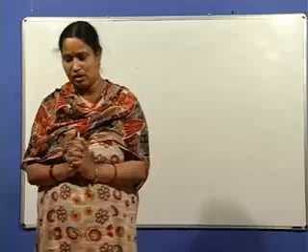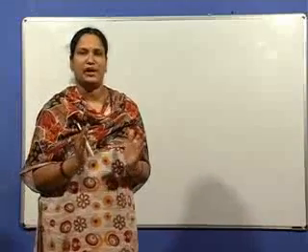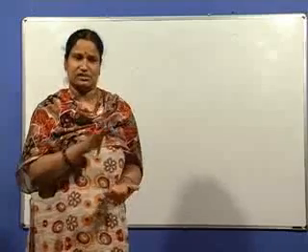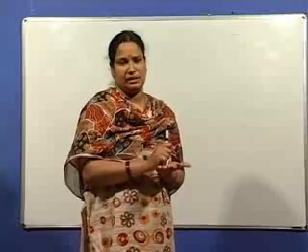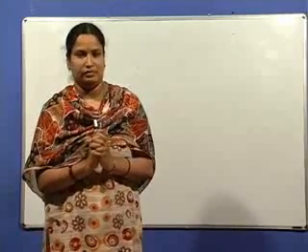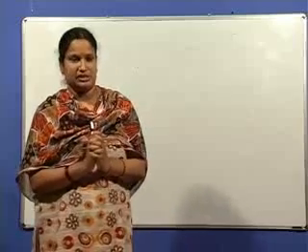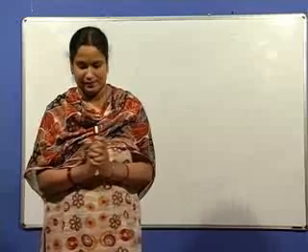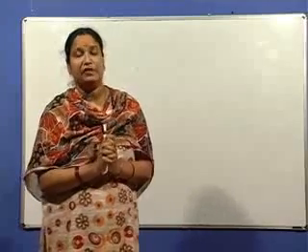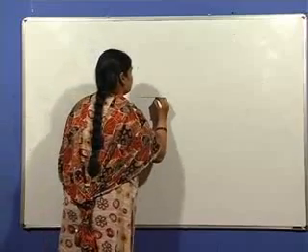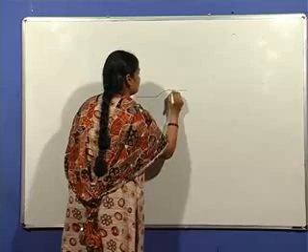What is this kink band? When the applied stress is nearly perpendicular to the principal atomic plane, the principal slip plane in the case of an HCP metal is the basal plane. So when the applied stress is nearly perpendicular to the basal plane of the HCP metal, this type of kink band is seen during compression loading. The metal shears by the formation of dislocation arrays that produce buckling along the slip plane direction that shears the metal several degrees away from its previous position. So there is slight buckling of the slip planes in the slip direction.